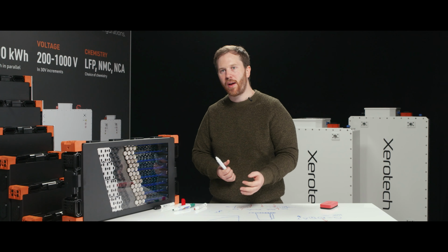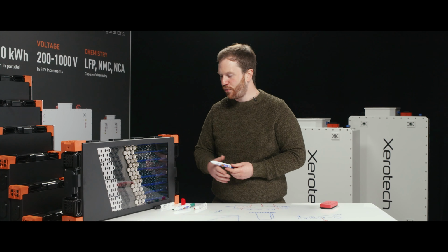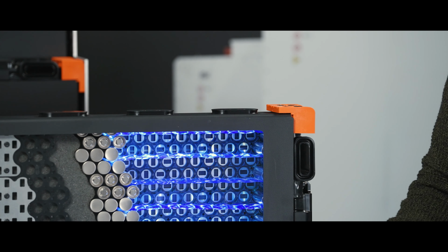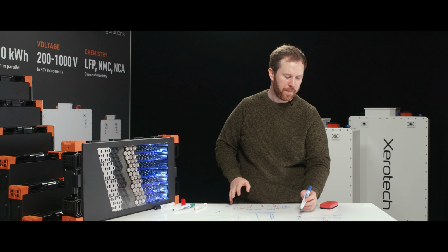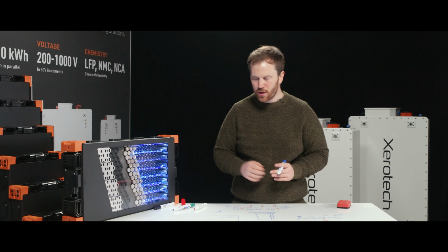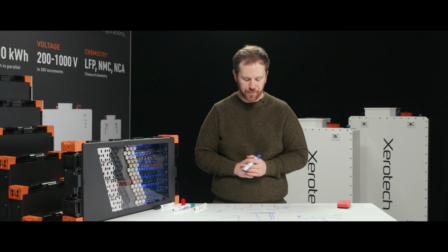And where that's really exciting is it means that we can have an order of magnitude higher flow rate through our modules, through our packs than anybody else, which means our temperature gradients are much lower. Our heat transfer is much higher in that case. So this is really, really important for controlling the temperature of battery modules.